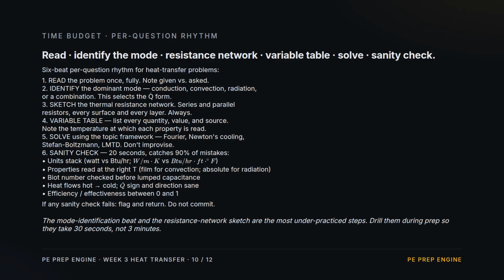Sanity check in 20 seconds. Unit stack, properties at the right temperature, Biot before lumped capacitance, heat flows hot to cold, efficiency or effectiveness between 0 and 1. If any check fails, flag and return.